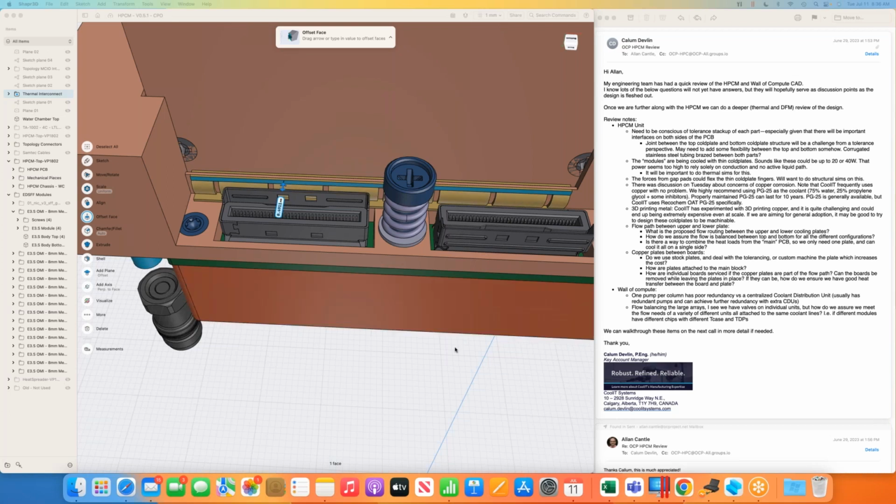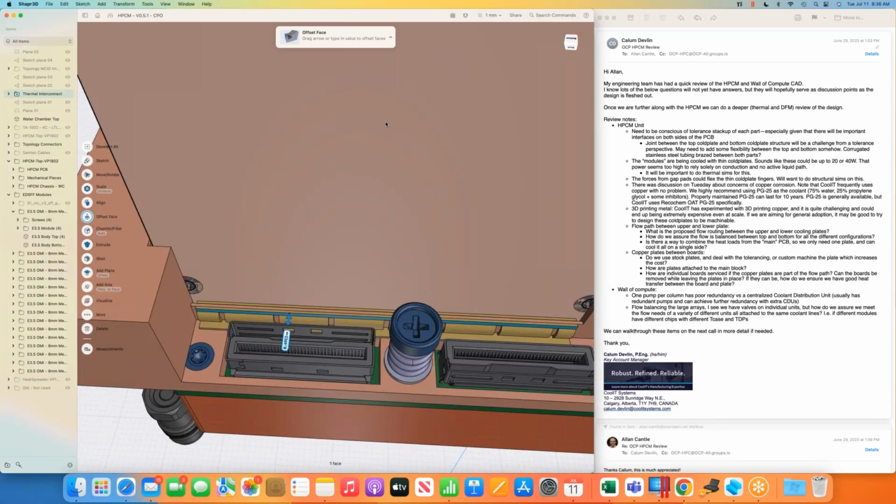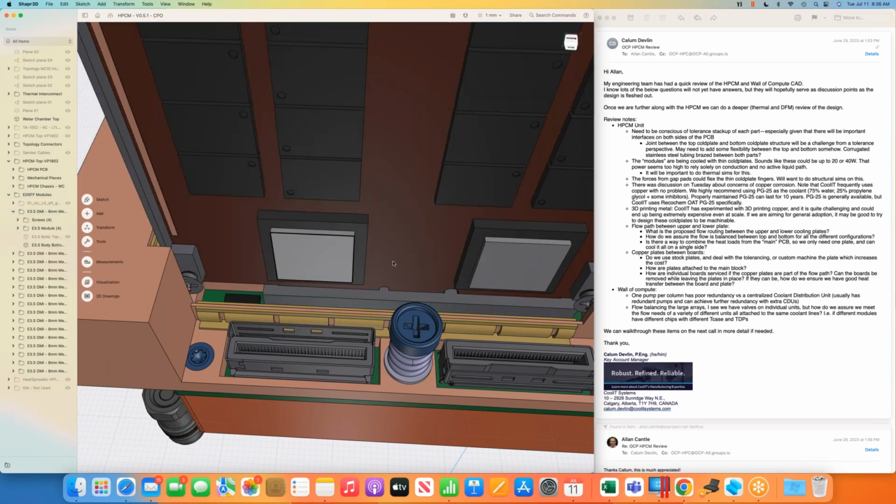How are you thinking that copper cold plate attaches to the card? Because you need to have the thermal connection. Oh yes, no, actually between underneath this copper for sure. Okay. Good point. So you would have a thermal grease giving you these, I'm assuming are going to be like 15 watts of the 25 watts or whatever, right?